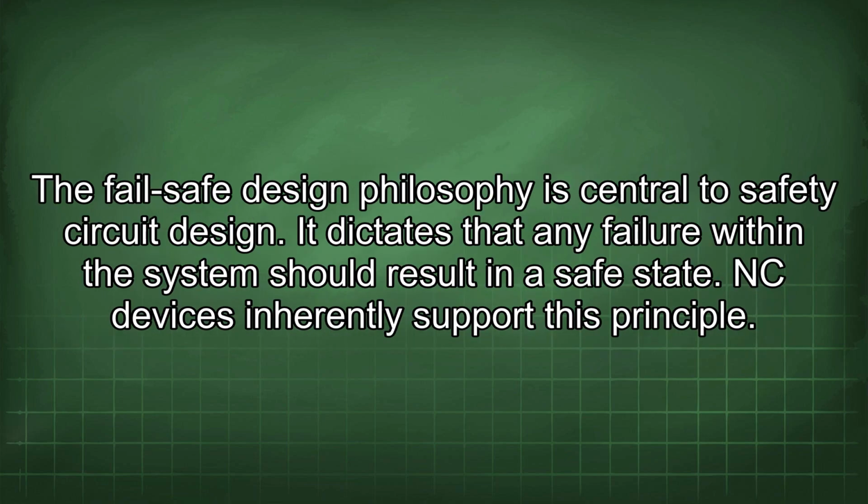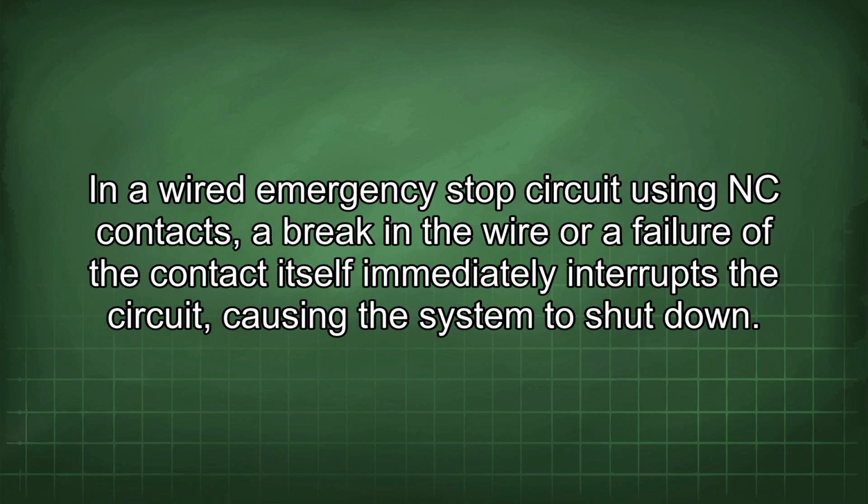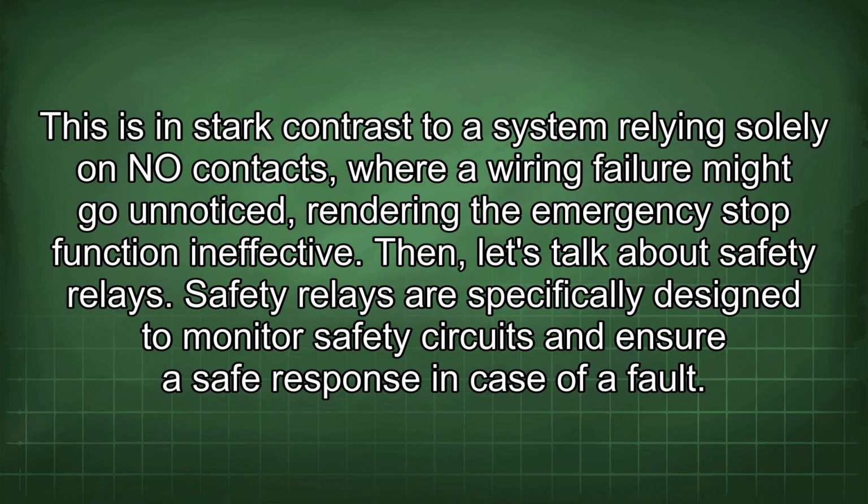The fail-safe design philosophy is central to safety circuit design. It dictates that any failure within the system should result in a safe state. NC devices inherently support this principle. In a wired emergency stop circuit using NC contacts, a break in the wire or a failure of the contact itself immediately interrupts the circuit, causing the system to shut down. This is in stark contrast to a system relying solely on NO contacts, where a wiring failure might go unnoticed, rendering the emergency stop function ineffective.